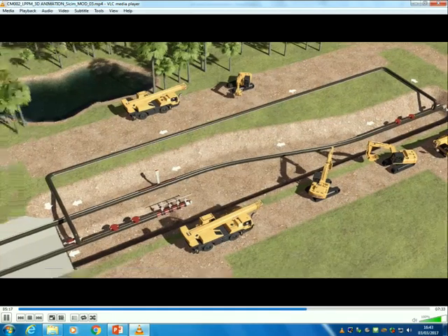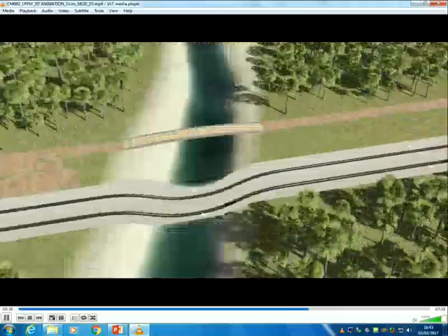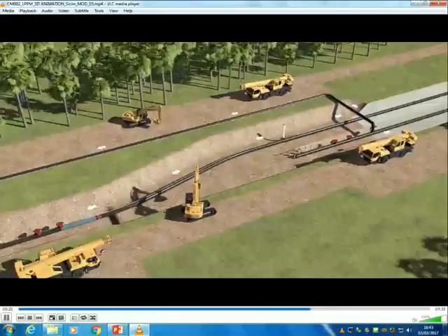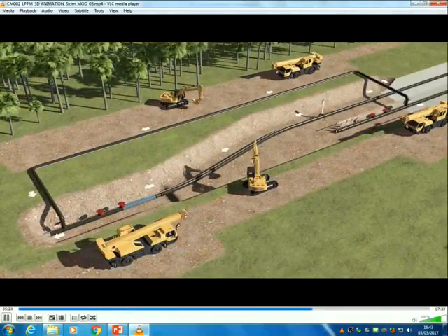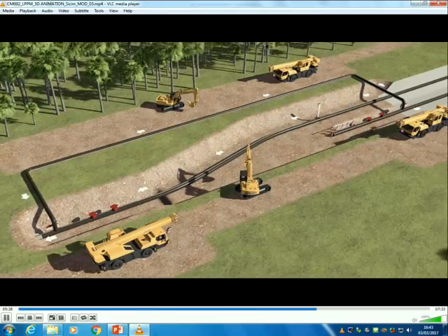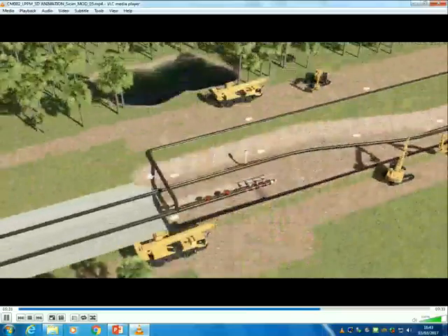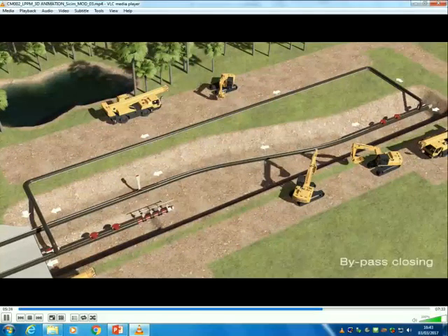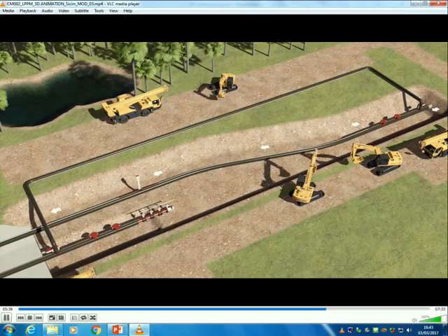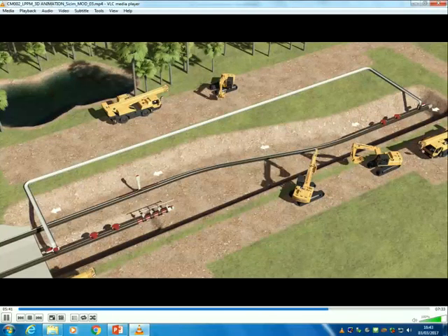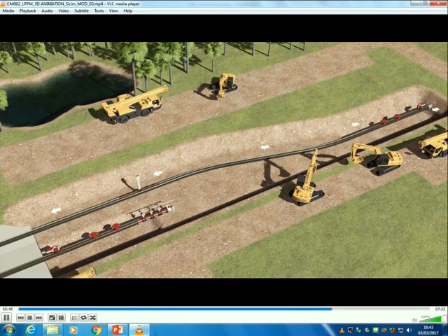And that is the new line taking over. So that pig which was dividing the oil from the water, that will carry on to the final receive end and they'll return it then. So what that's left them with is the bypass pipe work and all of the fitting arrangements, but also it's left them with a pipeline full of oil, which, you know, you can't leave a pipeline full of oil. You've got to get that oil out before you abandon it. So they will pick that oil out.